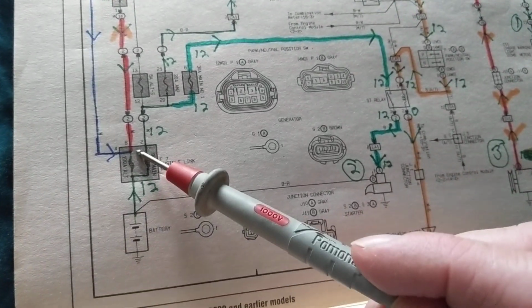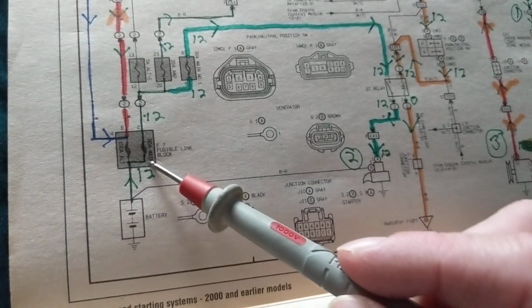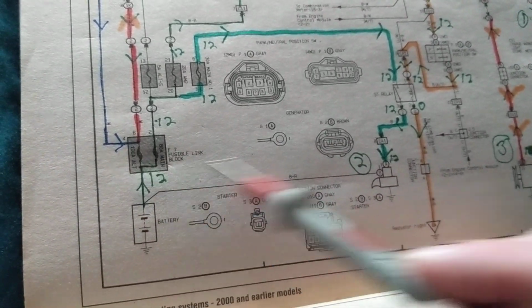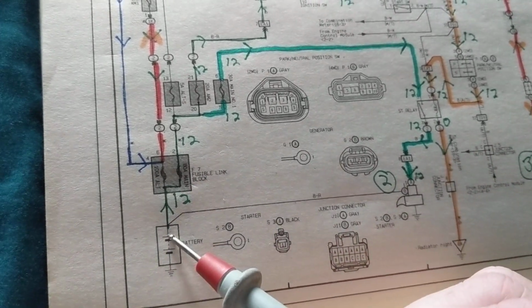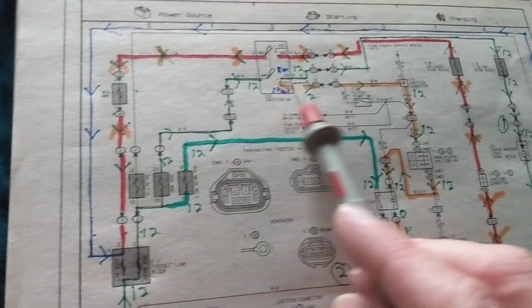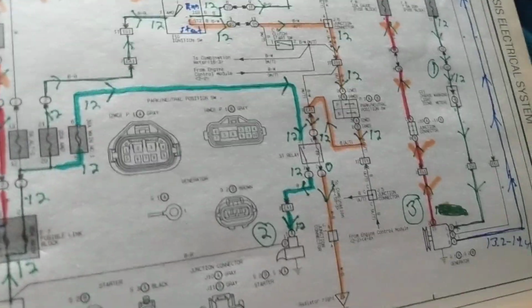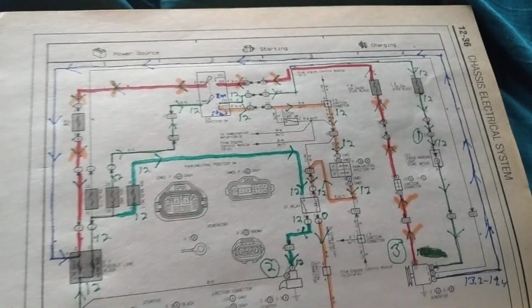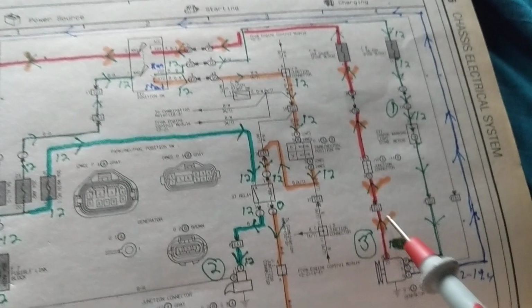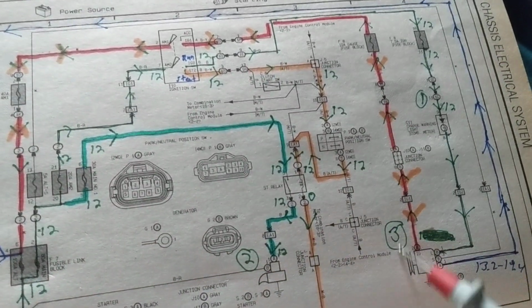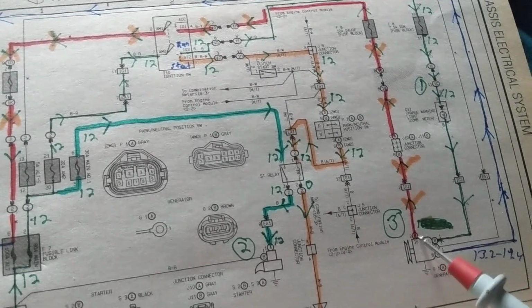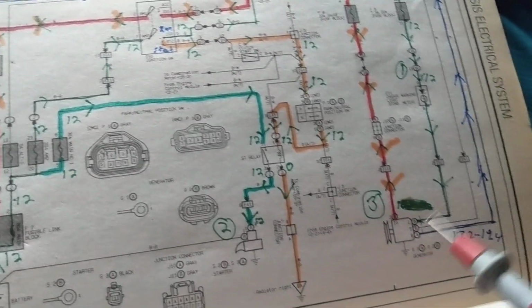We're now using it for what purpose? As a protection to the battery from the alternator when it recharges it. So it's going to go here and replenish the battery. And it's also going to take care of the accessories that need to be taken care of. After all, we're not done with this yet, because we still need some current to go through B plus also to go to the generator.